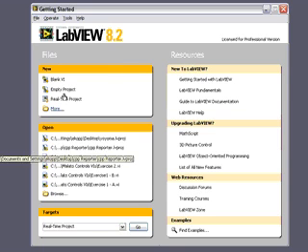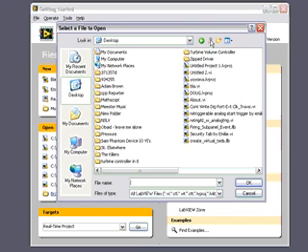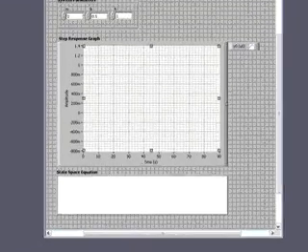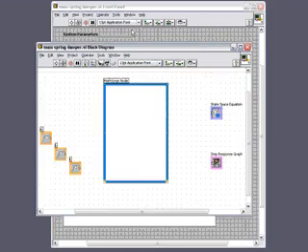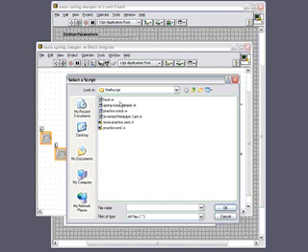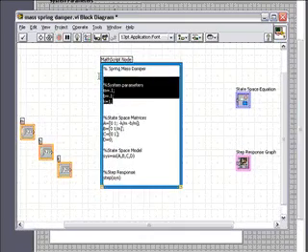Let's now move over to LabVIEW's graphical programming environment and examine how I can easily create a more interactive simulation by mixing graphical and textual programming. So first what I'll do is I'll load a skeletal VI here that I've already got going, and on the block diagram I'll use a MathScript node and import the M file that I just saved previously, spring mass damper .m.